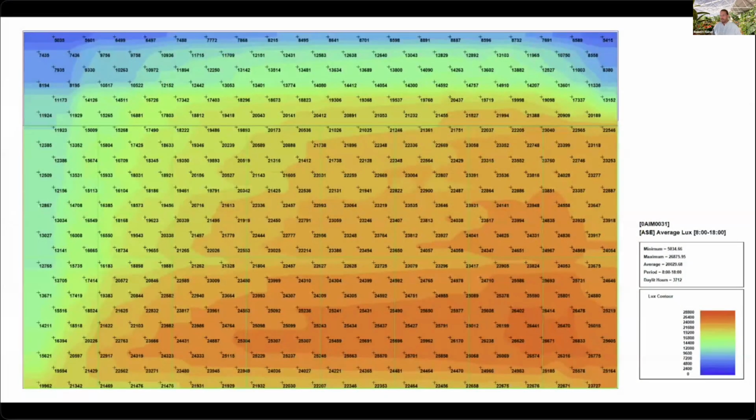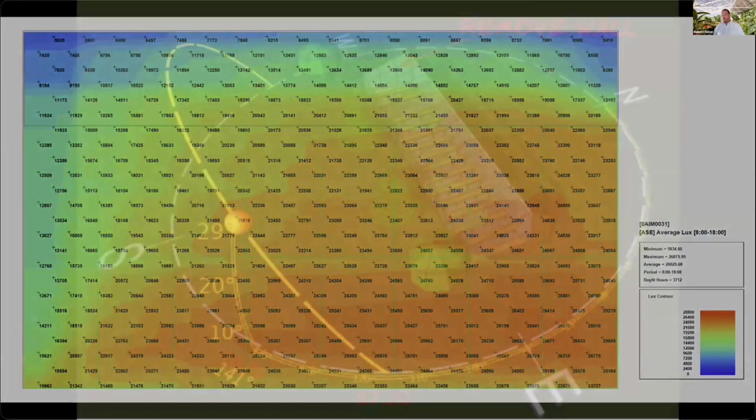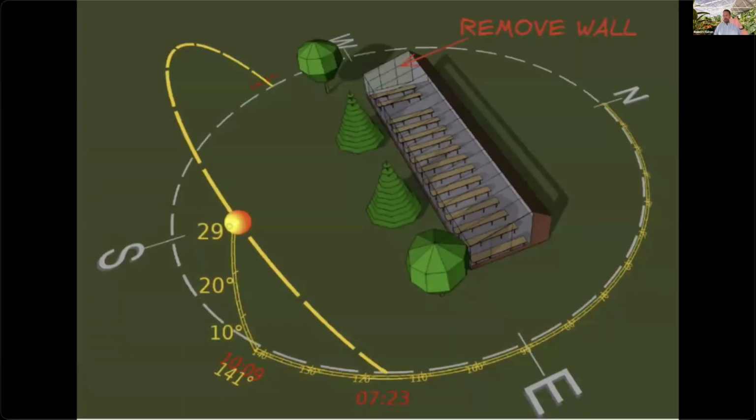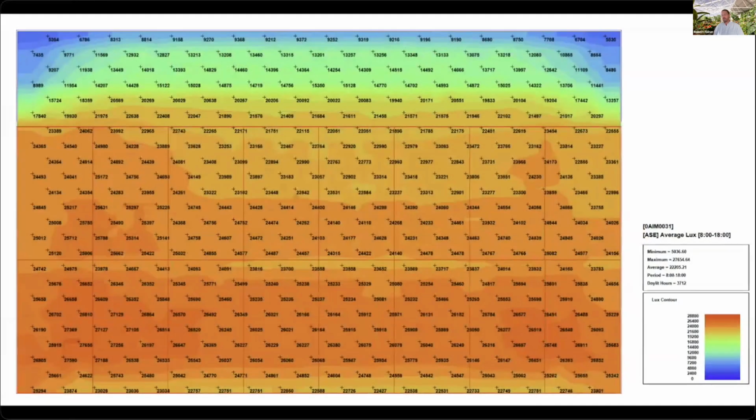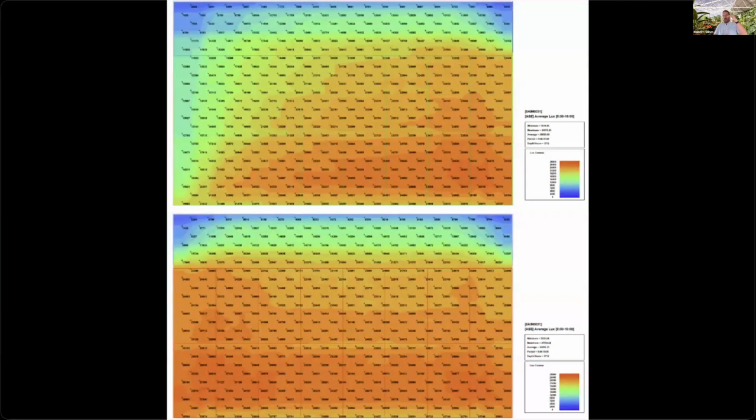And then the last thing I'm going to show is how we use this for lighting analysis. That was a building. And then when we remove just that one far wall and made glazing on that far side like it was on the other side, we have a nice even map of it. Now you can compare A versus B. So that in a nutshell is how Ceres utilizes IESVE for engineering projects and trying to understand and help designs, as consultants and architects and engineers work through projects. And that was all I prepared, Mary.